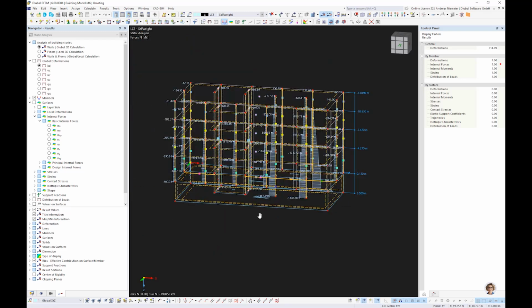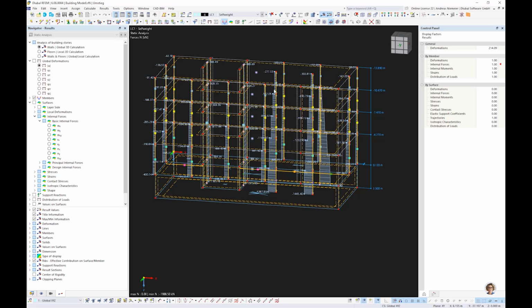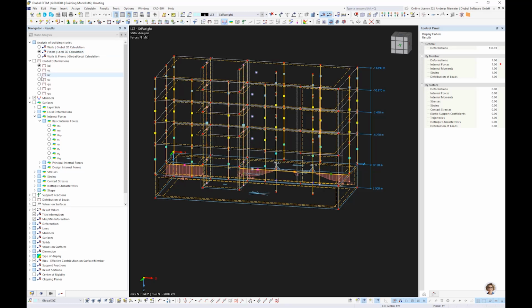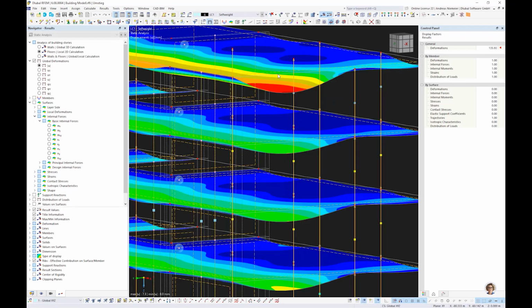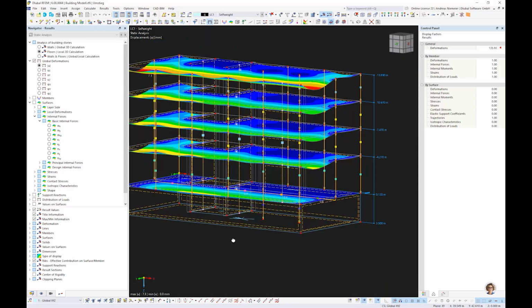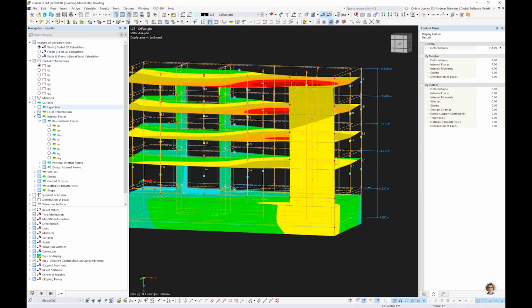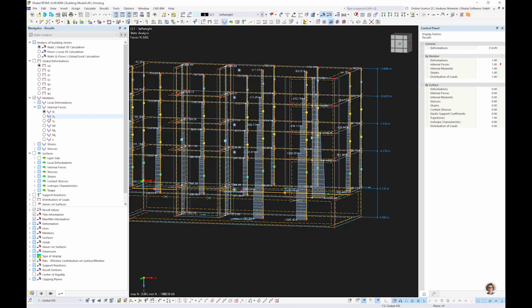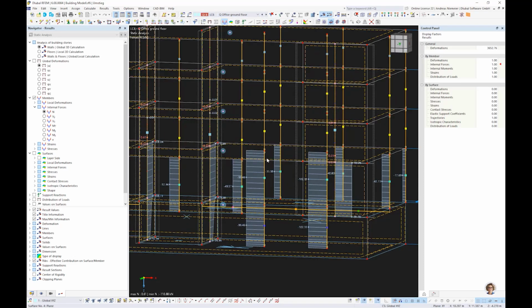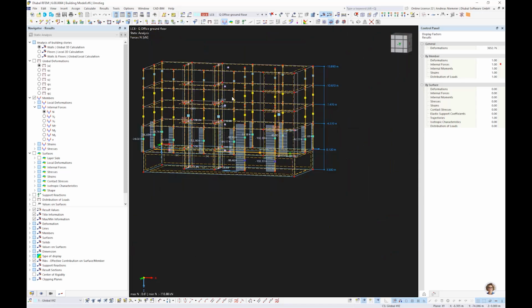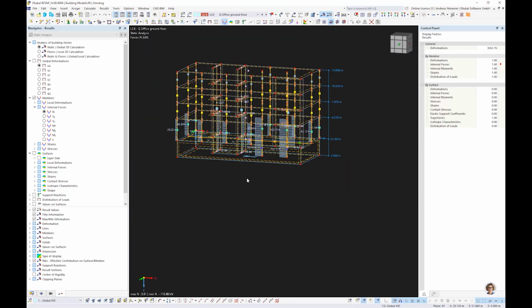And you see also here, for example, the increasing normal axial force gradient of columns, because I'm just visualizing the wall result. Also the columns belong to it, and here we have our slab or ceiling, where you see these are the ceilings here with deflection because of snow, but it acts separately. And if you visualize maybe the normal axial force, you see the lower slabs have no effect on the upper. For example, if we show a live load, you see the live load from this ceiling is going down but has no effect upwards. So with this type of calculation you can control the flow of forces.